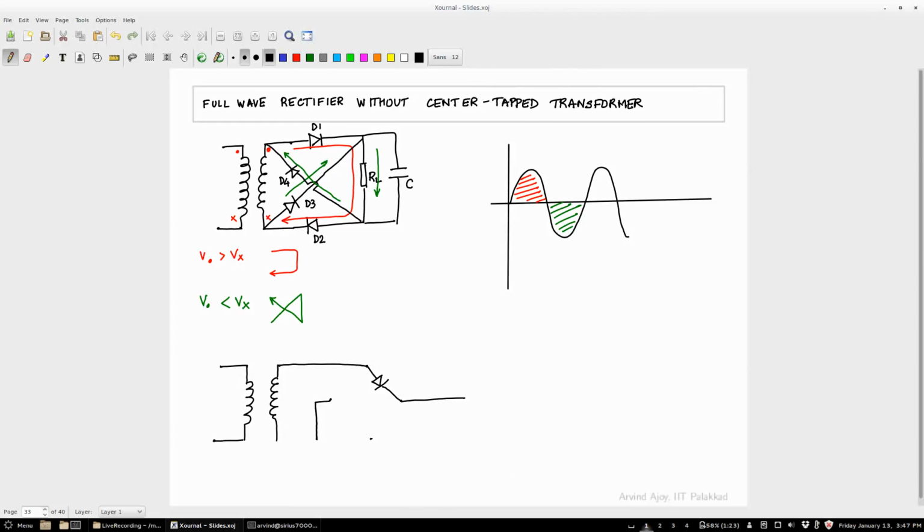So let me say I have 4 points. Okay. I'm drawing it in a very circular way, right? A diode like that, come to that point, okay, and have a load connected. So that is basically your resistor and capacitor. So the current then for the positive half cycle will flow like this through the diode, that's your D1, right? It will go through the load, come back like that, and what should happen? Another diode. It's the same circuit I am drawing, right? It will be D2, but I am just drawing it in a slightly different way. So that's here, connected here. Okay, so that diode is D2, and one can close this circuit.